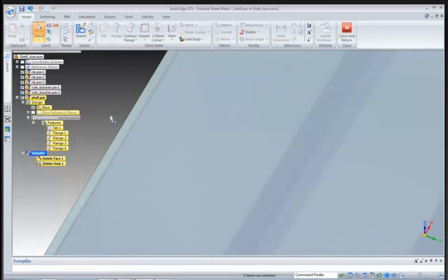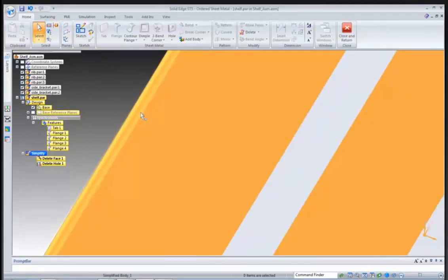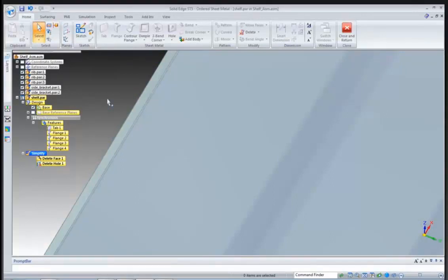And when I was talking about the elements and having a lot of elements, it's the same thing going through the thickness here. If I had to use a tetrahedral element, since they have degrees of freedom that are only translational, meaning that it's only x, y, and z displacement, I don't have the rotational degrees of freedom. If I want to capture the bending, I have to get 2 or 3 through the thickness. And you always hear that rule of thumb. You want to have 2 or 3 tetrahedrals through a thickness of some part. Well, if I had to get 2 or 3 and keep the aspect ratio okay through that thickness there, I'm going to have very tiny elements.